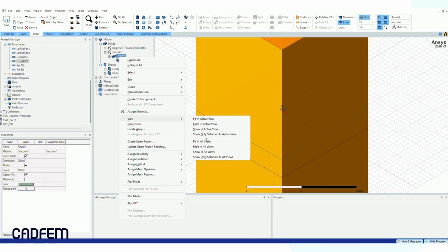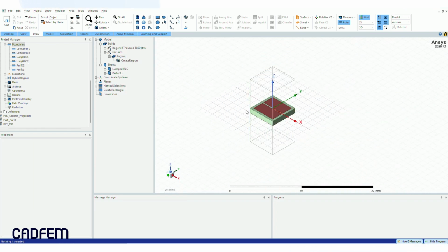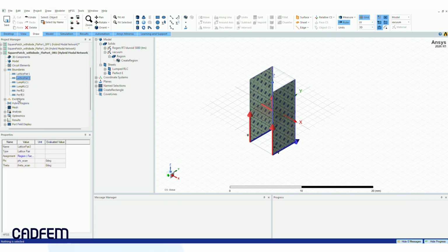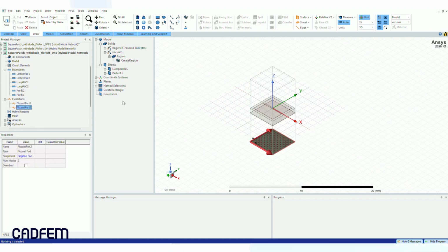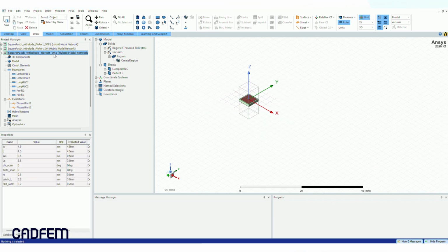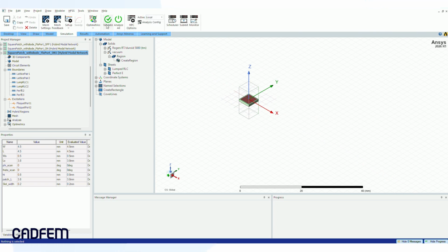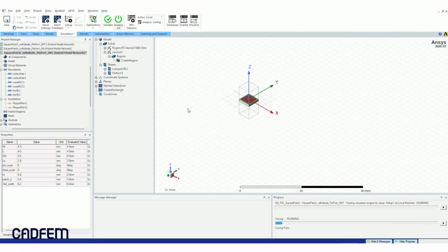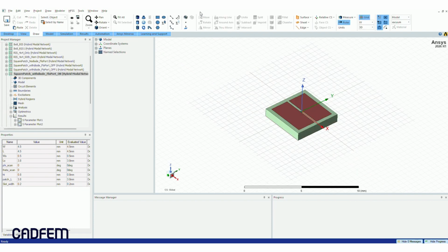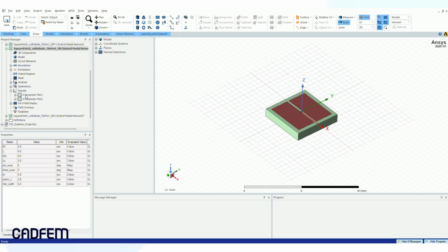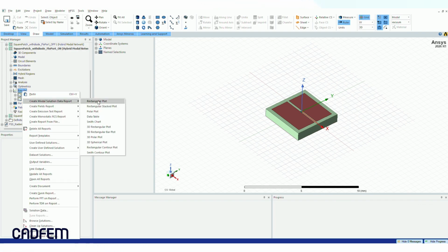Now we pivot to modeling the unit cell explicitly in its active tuned on state. By accessing the lumped RLC boundary properties assigned to our tuning slit, we update the values to match our forward biased pin diode parameters. We deactivate the capacitive variables, assign a low forward resistance of 4.2 ohms, and input a parasitic inductance of 0.05 nanohenries. These equivalent circuit parameters accurately represent the conductive behavior of the diode when forward biased, enabling current flow across the tuning gap.